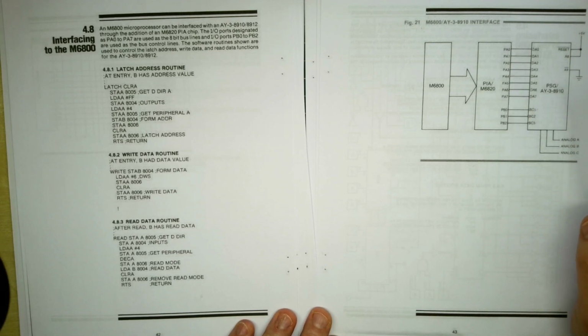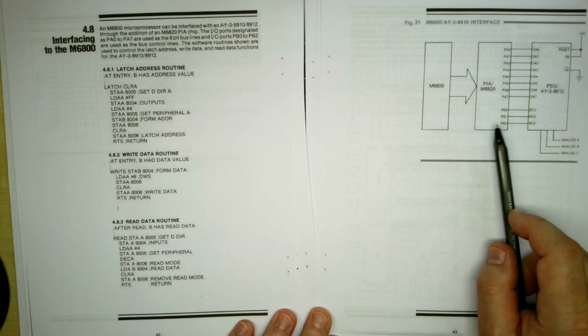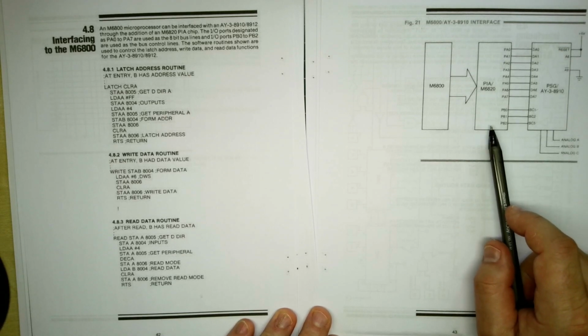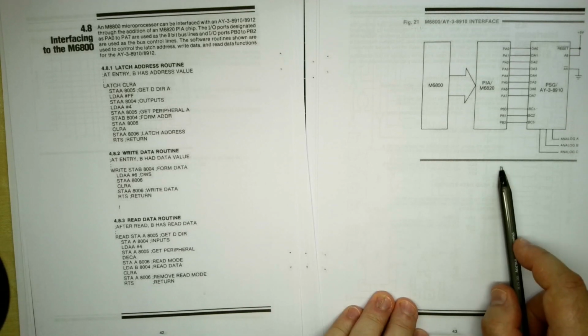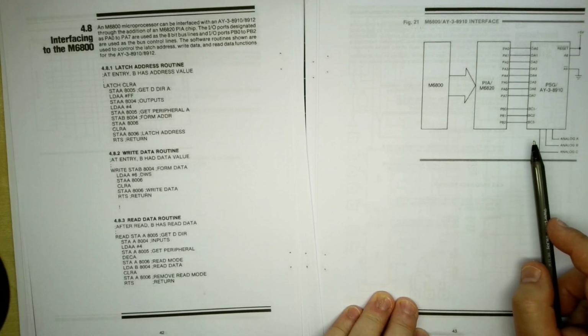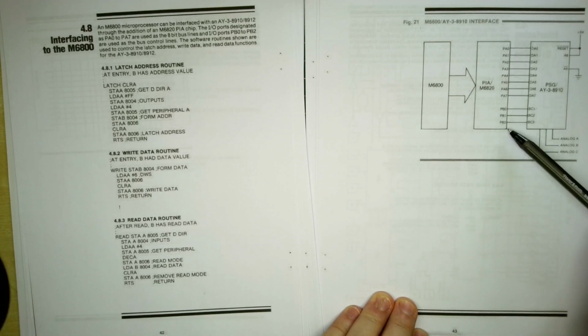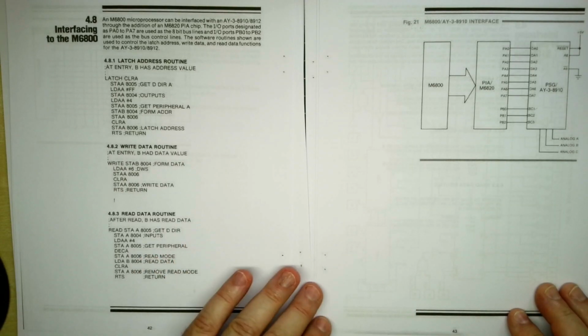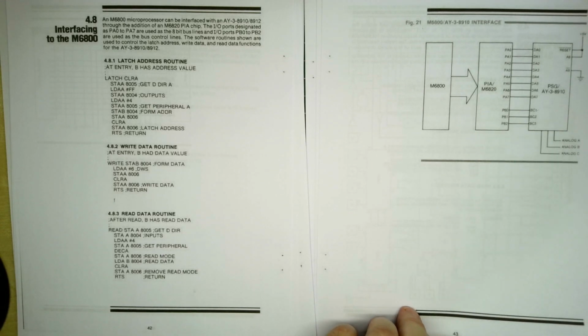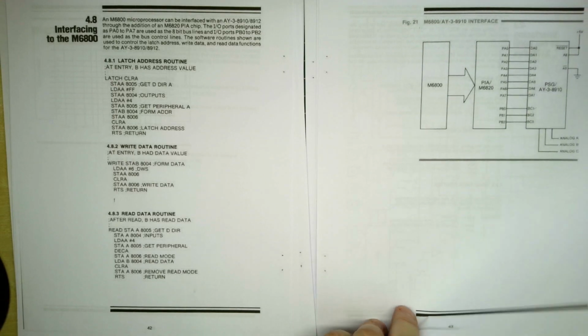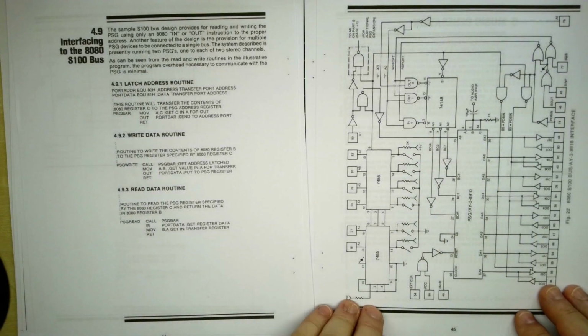So although initially I didn't want to go down this approach, with the timing issues that we identified in the datasheet, and also the fact that we're going to need another 4 or 5 bits for input from the joystick, I thought, well, at least I could use port B 3 to 7 for the joystick as well. And there is obviously a little bit of assembly language code there. So we're going to use the peripheral interface adapter, and that should make the programming a bit easier. This is an example of an Intel 8080 one, which was a little more complicated.